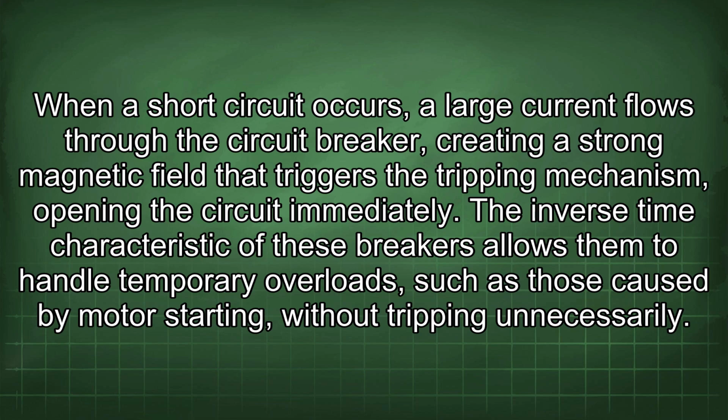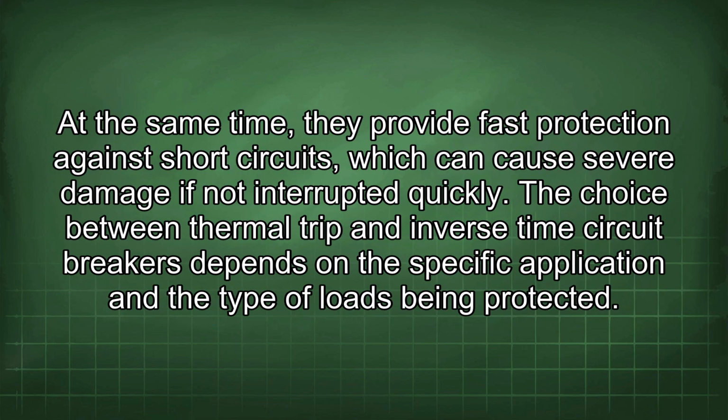The inverse time characteristic of these breakers allows them to handle temporary overloads, such as those caused by motor starting, without tripping unnecessarily. At the same time, they provide fast protection against short circuits, which can cause severe damage if not interrupted quickly. The choice between thermal trip and inverse time circuit breakers depends on the specific application and the type of loads being protected.